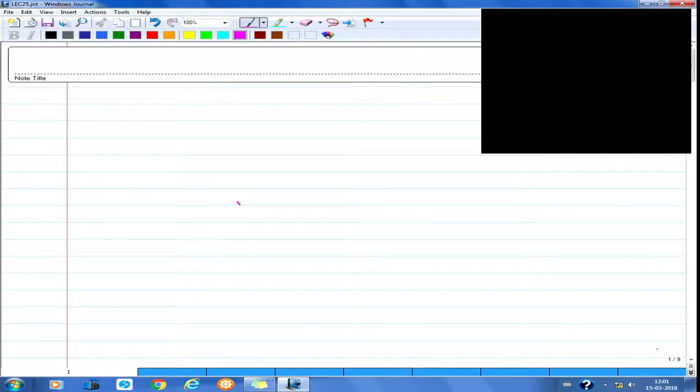it is more difficult when we go more than 8 nodes. 9 nodes is a Lagrangian element, so you can easily write that, but when we go for only the nodes on the boundaries of the element, writing the shape function is actually a bit difficult. But then what you can do is assume a polynomial and then express all the constants in terms of the values of the variable at the node points, and then from that you evaluate your shape function. So that can easily be done. But writing the shape functions from inspection like what we were doing is not easy for number of nodes more than say 9, particularly for the serendipity class of elements.